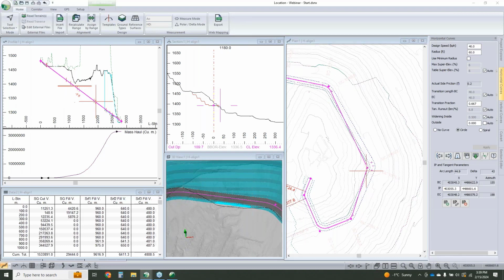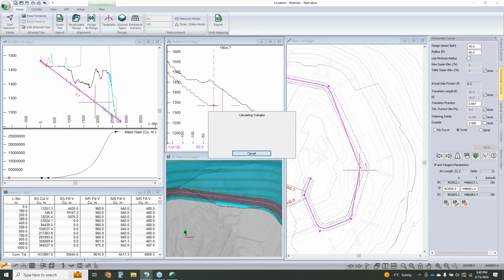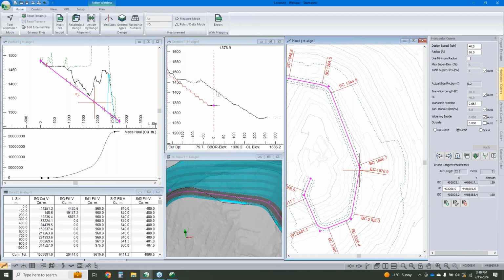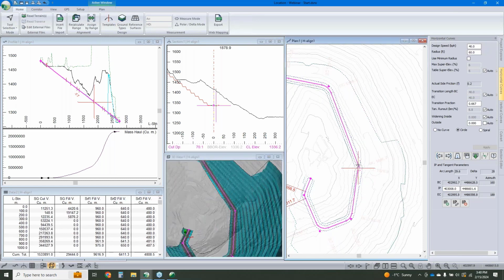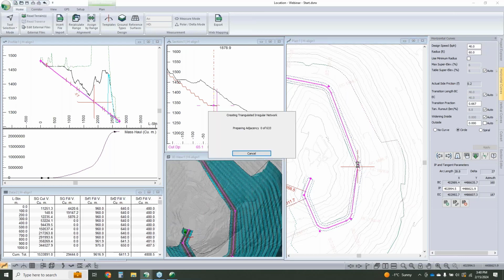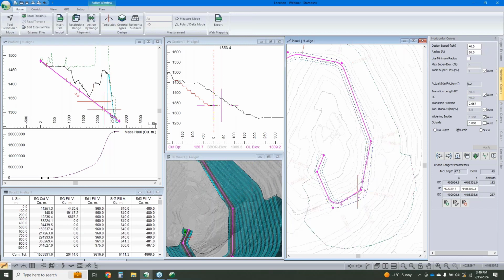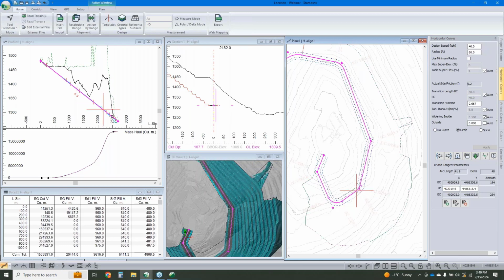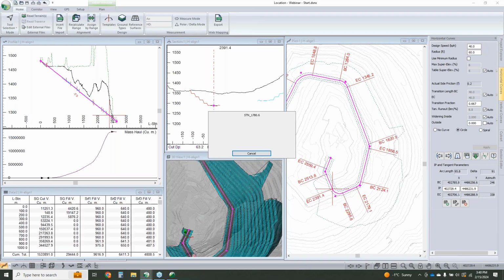And while Matt just does a little bit more dynamic editing of the alignment, I'm actually going to tackle what I'm going to call easy questions. So for our audience, if you are wondering the machine specs that we recommend for RoadEng. So historically, we've recommended really modest specs, kind of 8 gigs of RAM, standard business laptop. As we look at Path Explorer, which was the question here that I'm addressing, we are recommending slightly higher specifications. So Path Explorer is going to look to use a relatively large amount of memory. So the more you have, the larger problems you can solve.